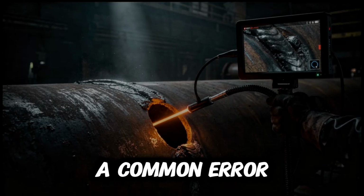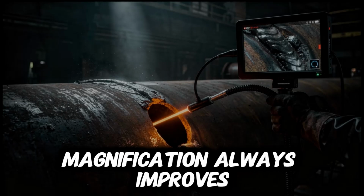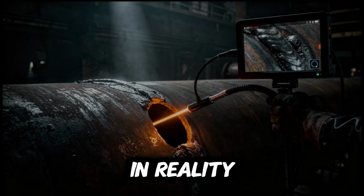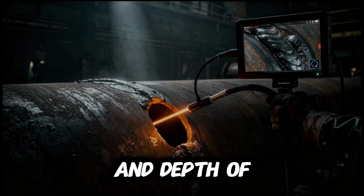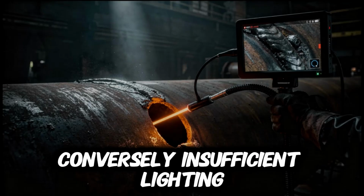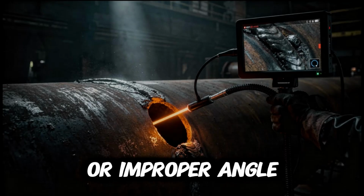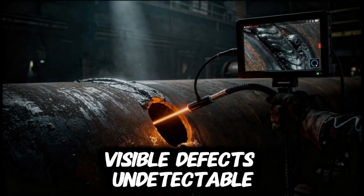Yes, it is a common error to assume higher magnification always improves detection. In reality, excessive magnification reduces field of view and depth of field, making it harder to locate anomalies. Conversely, insufficient lighting or improper angle selection can render visible defects undetectable.